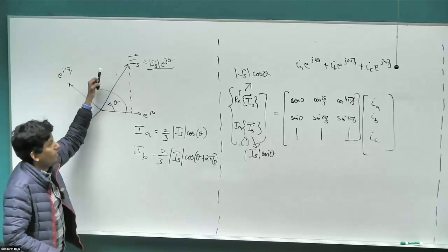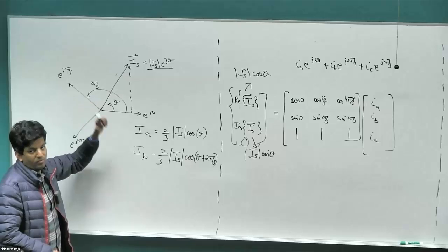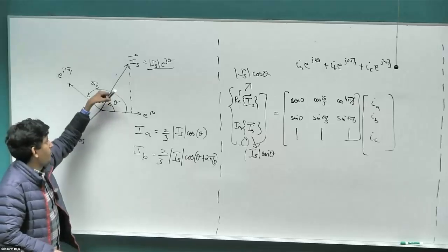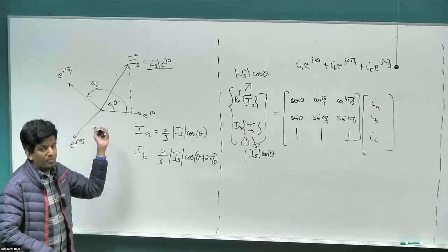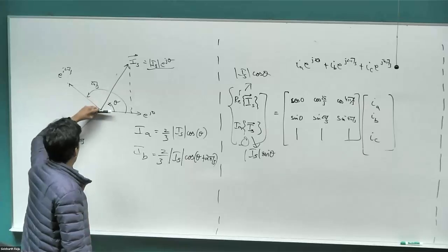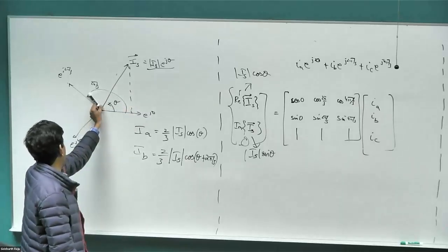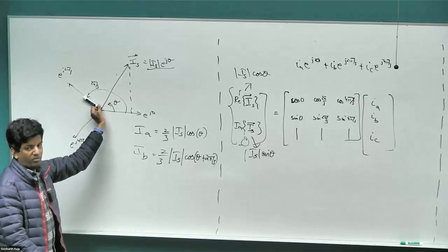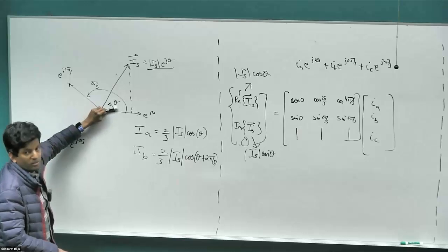And I think in problem 3 you basically had to plug in three sinusoidal currents and figure out how the space vector moves. You would have seen the space vector has a fixed magnitude, but the angle would be e^(j(ωt + π/2)) or something, which says that at time t equal to 0, the space vector would have been here. As time goes on, it keeps on rotating. At ωt equal to 2π/3, it would have reached here, and then later it will move here at 4π/3 and then come back to here again.